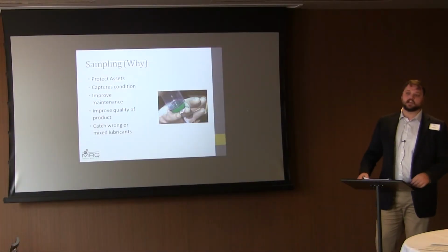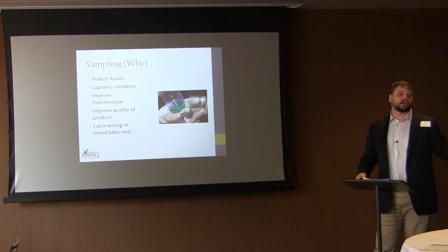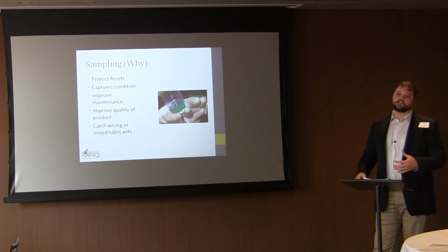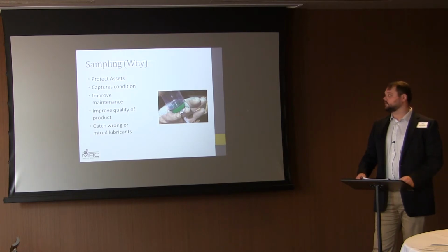So there's lots of little things like that, or contamination. If you've got a lot of moisture coming in from your environment, or dust or anything like that, depending on your specific applications, you want to try to minimize that contamination. Obviously, if your lubricant gets contaminated, it's not going to perform well, and then you're going to have issues either with your product or the machinery itself.